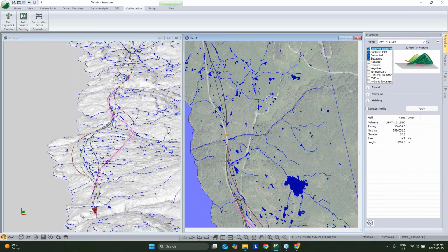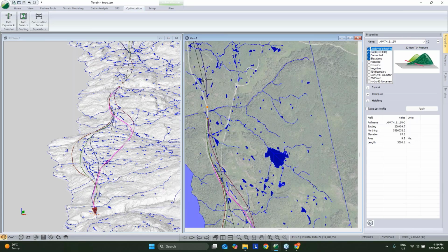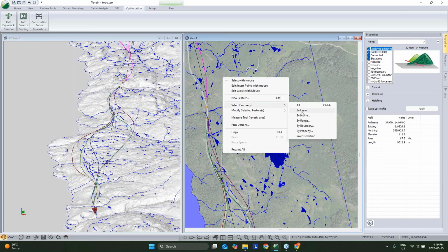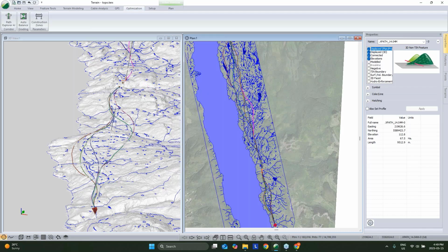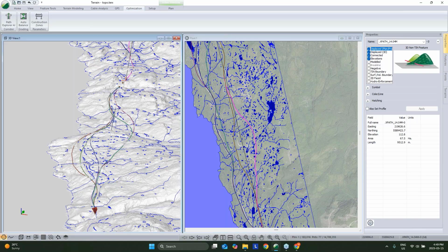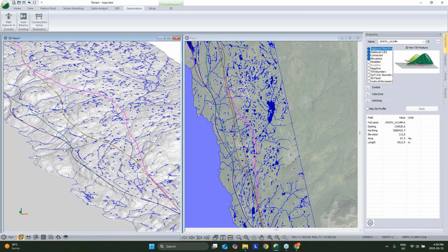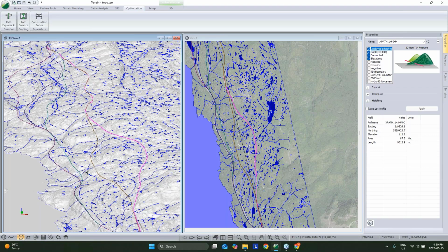And then on the other end of things, we can look at these solutions, select feature by name, and well, let's see which one here is expected to be the cheapest. Again, not the one that's following the existing geometry, but instead we're swinging high and staying up on that plateau rather than in the gnarlier terrain where the existing road is.